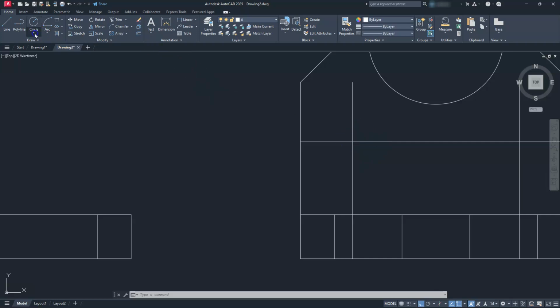Okay, let's go ahead and place my circle here. So I'll go ahead and choose circle center diameter. And this is where reading those notes is going to come in. I'll go to this intersection and place my diameter circle at 16. Then I'll go back to the circle center diameter, go right on the inside of here, and place that circle in there at 8.